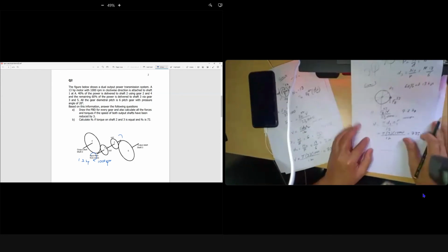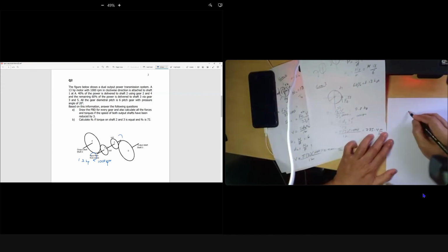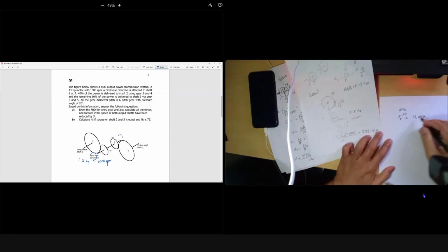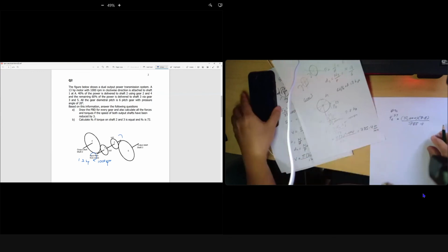So you got your V. From here, your F tangent 53 equals 33,000 times 7.8 horsepower over your V, 785.4 feet per minute.